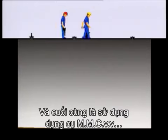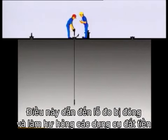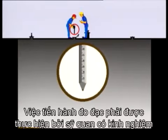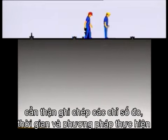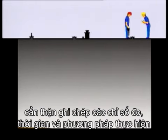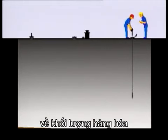A final point about using the MMC. It is bad practice to leave it unattended while fitted to the vapor control valve. The valve can close and damage a very expensive instrument. Measuring cargo should be done by an experienced officer. Great care should be taken to record results, times and methods used. These are valuable facts to use in any dispute on cargo quantities.